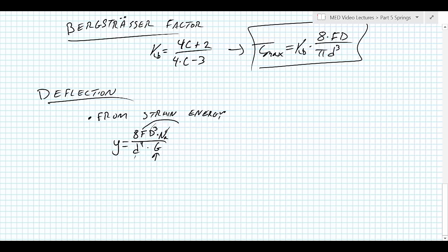So if I was to move this F over here, we might see something that's a little bit more common way to describe it, which is the force that a spring resists with, or that it takes to deflect a spring, either way, since it's an equals sign, is some spring rate times the deflection that we want to get, or x. It doesn't matter, obviously, which one you use.